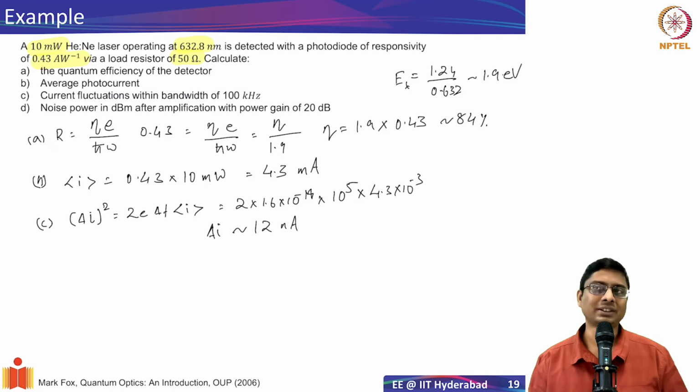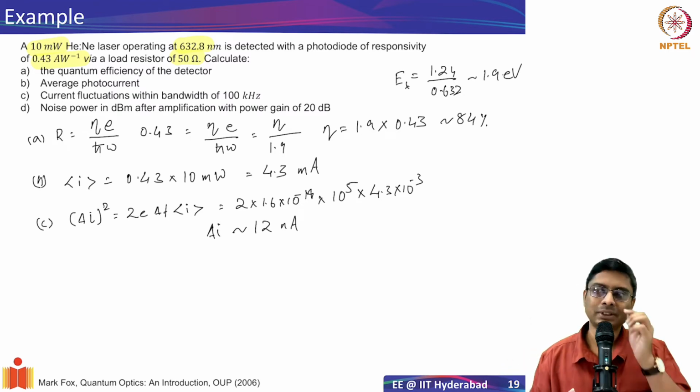Otherwise, if you take a wide bandwidth in your detector, where all the frequencies are allowed, then your signal to noise ratio deteriorates, because you are adding up noise in every frequency range and the signal is only in one place. So in measurements, it's useful to have bandwidth limited cases.